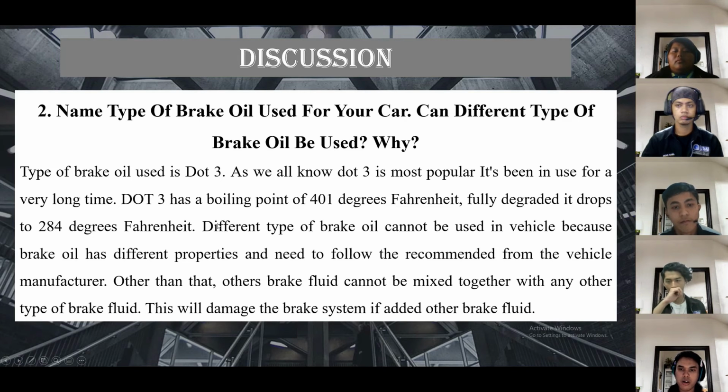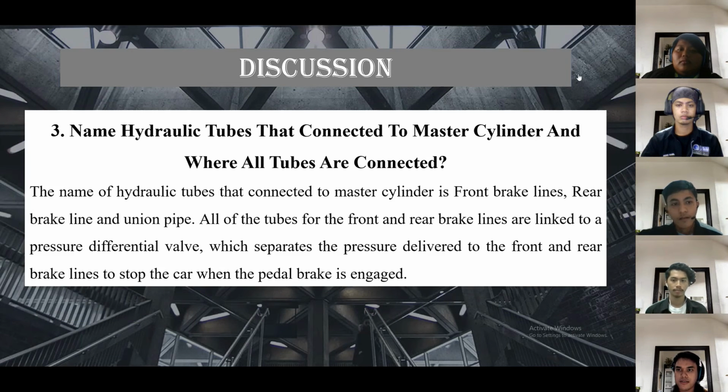Different types of brake oil cannot be used in a vehicle because brake oil has different properties and needs to follow the recommendation from the vehicle manufacturer. Other than that, brake fluid cannot be mixed with any other type of brake fluid. This will damage the brake system if other brake fluid is added. Next I will pass to the next presenter, Hafizin.